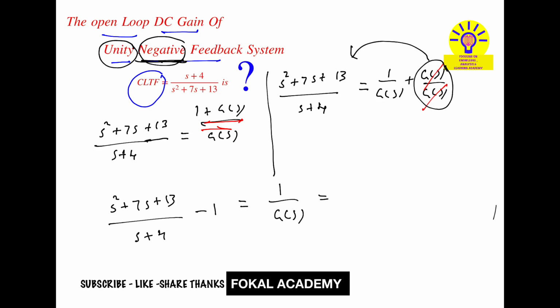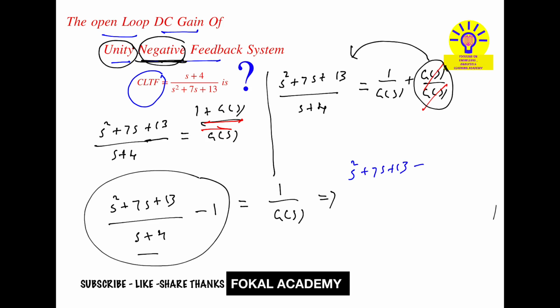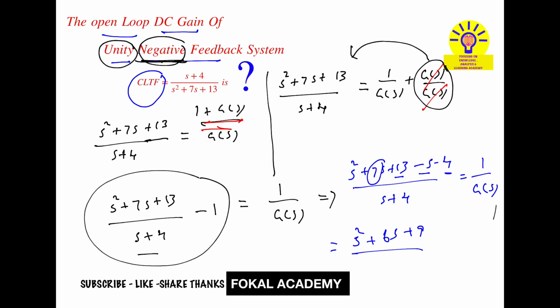By simplifying this, taking LCM (s + 4), it becomes (s square + 7s + 13 minus s minus 4) upon (s + 4), that's equal to 1 by G(s). So it becomes s square plus 7s minus s, that is 6s, plus 13 minus 4, that is plus 9, upon (s + 4), equal to 1 by G(s).